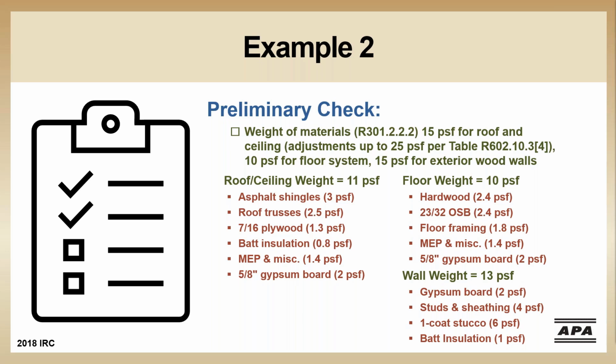Obviously, if you want to make this building solar ready, or you're putting solar on the roof, that also needs to get included in this weight takeoff. We're also sticking here with a pretty light floor covering of carpet and some laminate over 23/32 category OSB, and I-joist with a gypsum board ceiling attached to the underside.